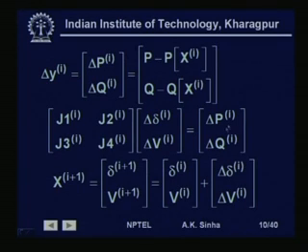So, Ax is equal to y is the form, and we have seen how we can solve it using the Gauss elimination method. Once we solve for this x, that is delta delta and delta V at ith iteration, then we can find the value of x, which is again delta and V at i plus 1th iteration, as equal to the value of delta and V at ith iteration plus the value of delta delta at ith iteration and delta V at ith iteration.